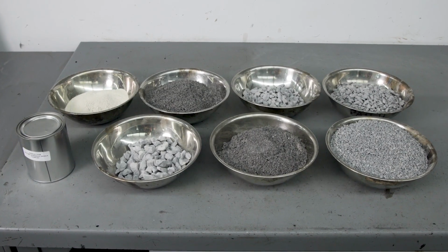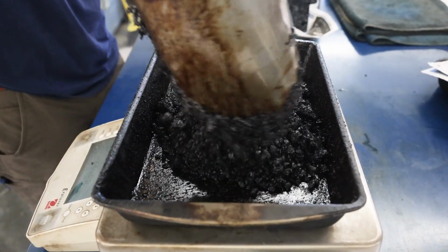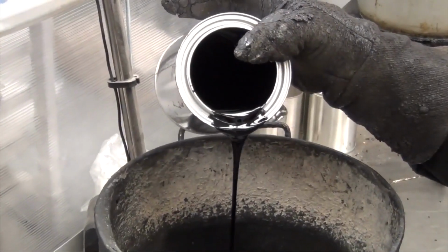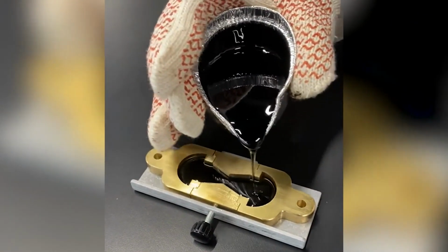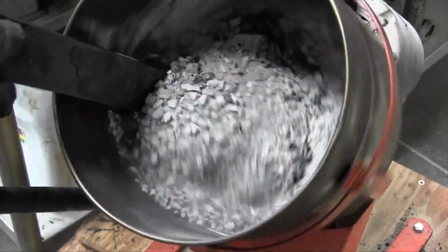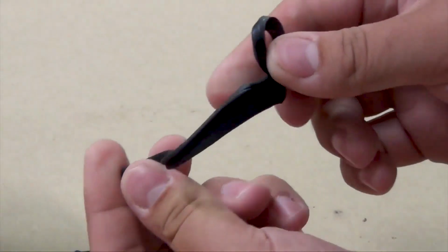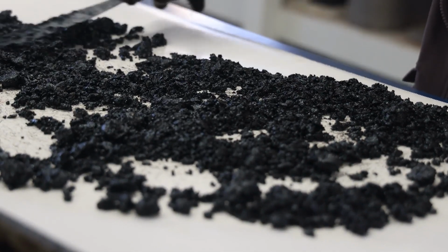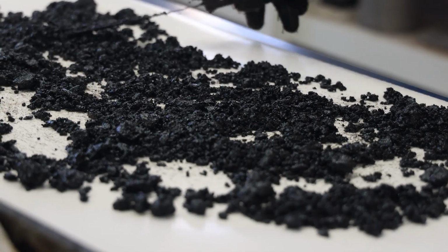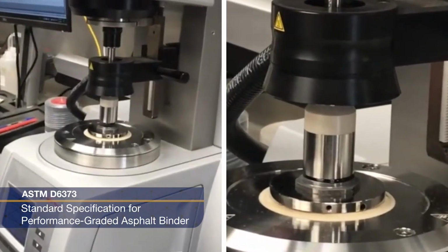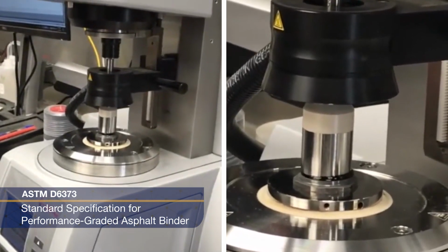Let's look at how asphalt ingredients impact a mix design and the resulting job mix formula. Asphalt binder, or bitumen, is produced by refining crude oil. It binds aggregate to create asphalt pavement, stabilizing it to prevent rutting while remaining flexible to resist cracking. The binder influences pavement stiffness, temperature resistance, and ductility, and must meet FAA requirements per ASTM D6373.